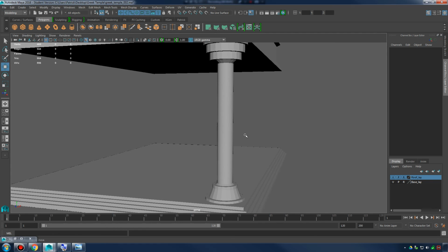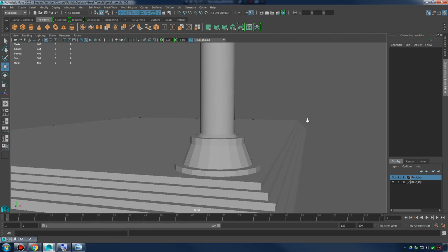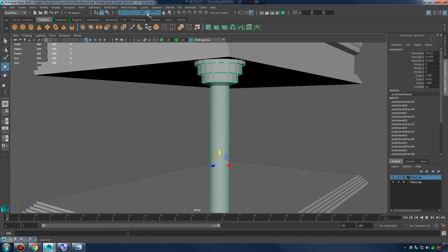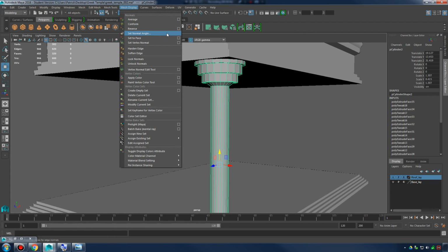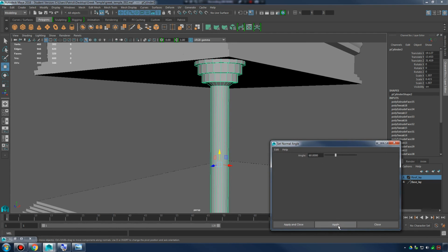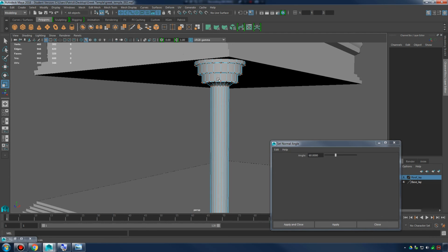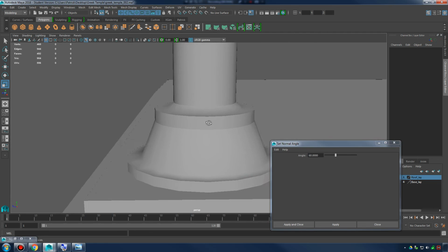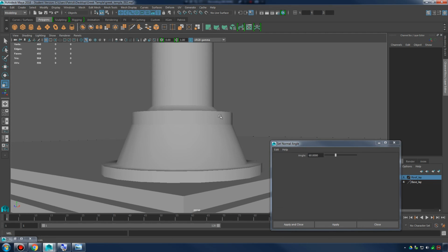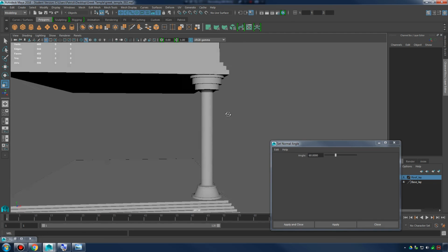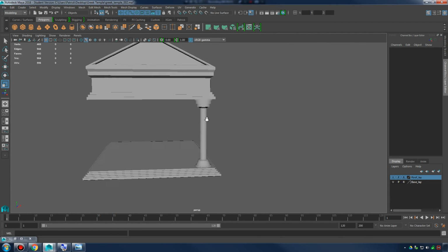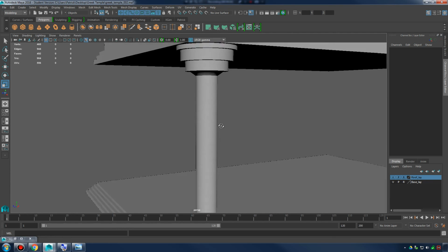They're looking a little rigid, so again, we need to figure out how to get these rigid edges out of it. There's an easy way to do that. If I select my object and go to Mesh Display, I'm going to set my normal angle to about 60. And that'll get rid of those crinkles, but keep the hard edges where we want them, like right there. Alright, great. So there's some columns there, and you guys just have fun doing all kinds of columns.